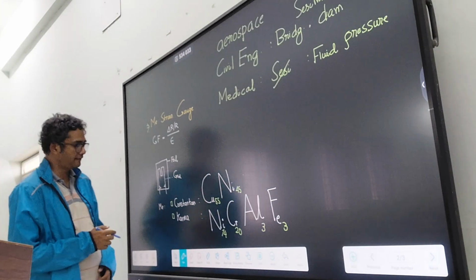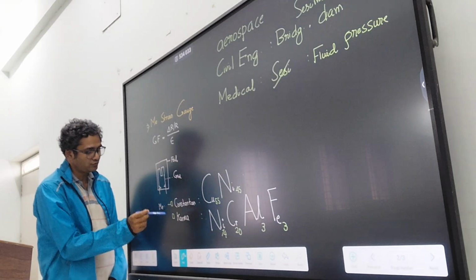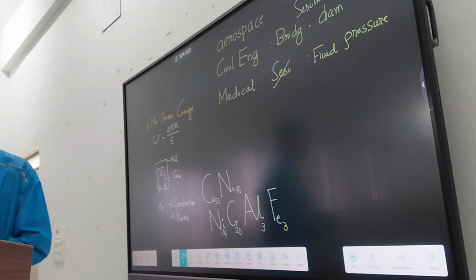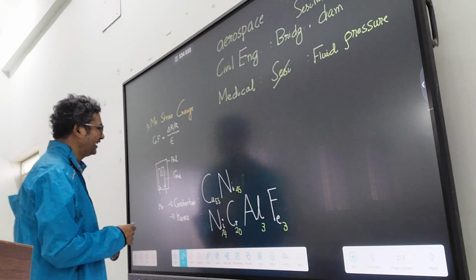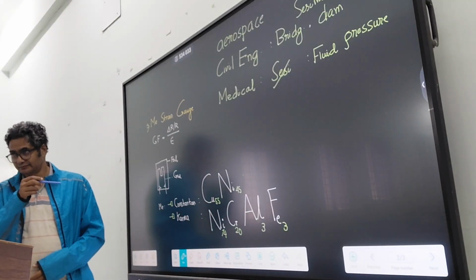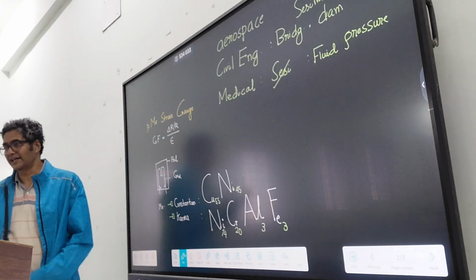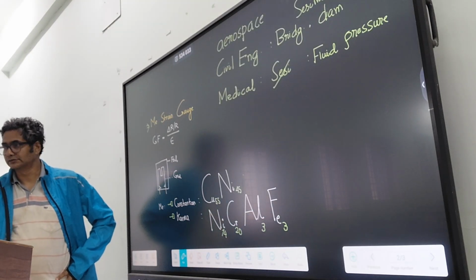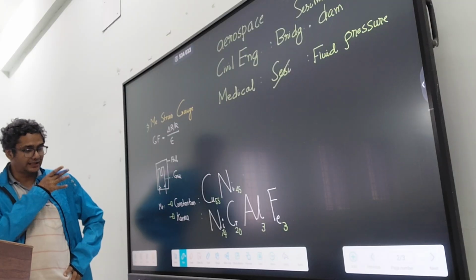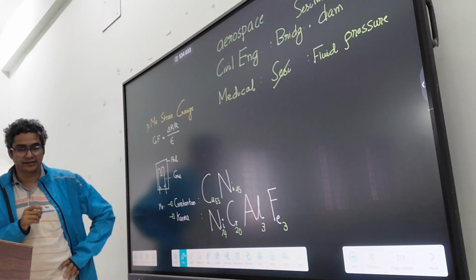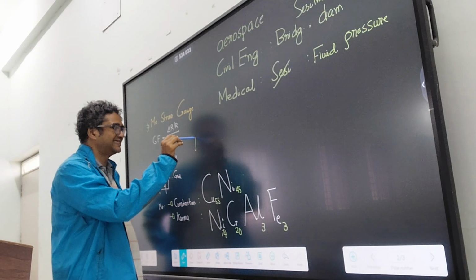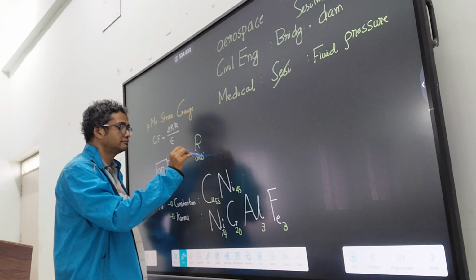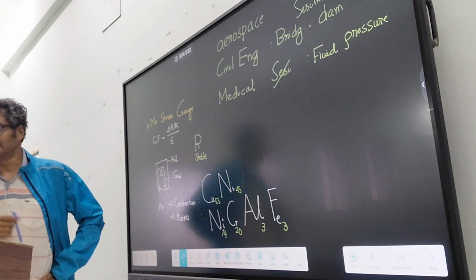Now the question is, we have understood that these two types of alloys are used for a metallic strain sensor. And what is its gauge factor? There has to be a change in resistance due to some mechanical strain. So why these two? Why not any other, copper? Because we need to understand that we can have only those materials whose resistance is stable with respect to temperature.